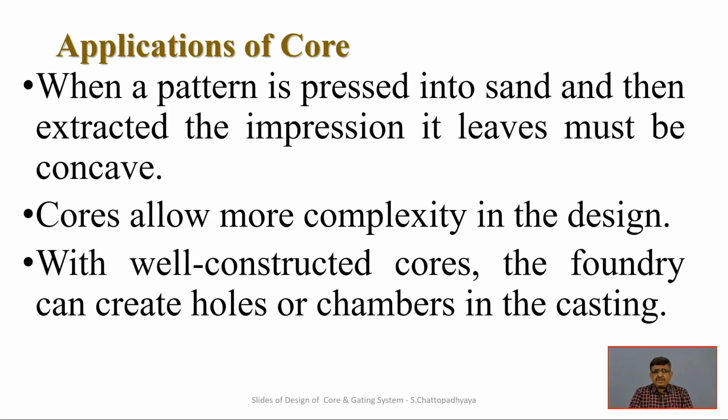What is the application? When a pattern is pressed into the sand and then extracted, the impression it leaves must be concave, not convex, for easy withdrawal of the pattern. The main challenge of the pattern is appropriate withdrawal, where the pattern is reusable, not sacrificial.